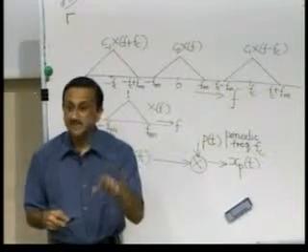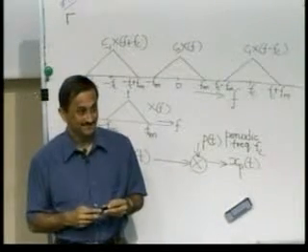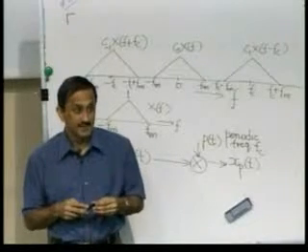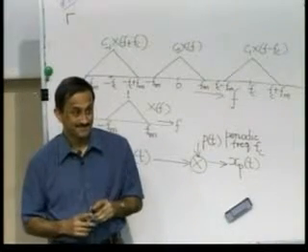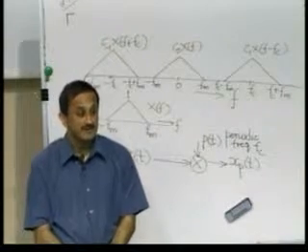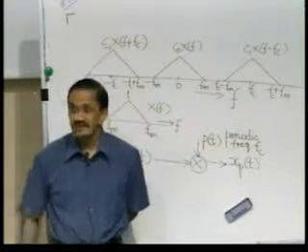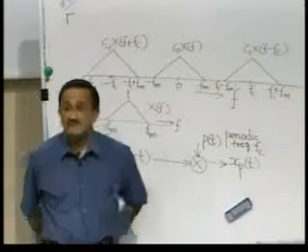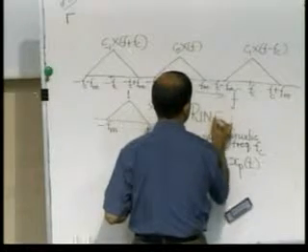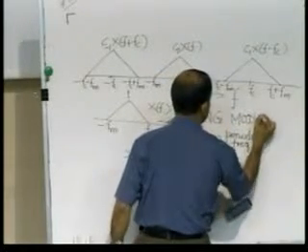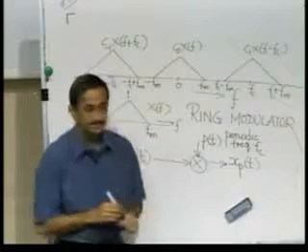One is that I have not needed to multiply explicitly with a sine wave. So, I have not needed to generate a sine wave at all, which cannot always be done very easily. Generation of a sine wave requires construction of an accurate oscillator. So, here it illustrates that you do not need to construct the oscillator very accurately. In fact, you can have a very crude oscillator. You do not even need to have an oscillator. You could just have a gating pattern which can be built out of diodes. In fact, this is the principle of what is called the ring modulator in communication.